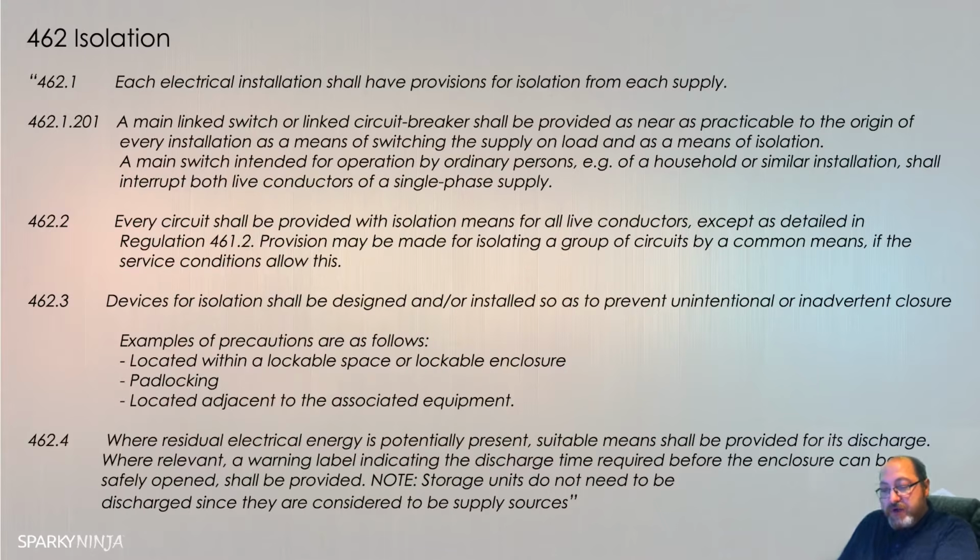Where residual electrical energy is potentially dangerous or potentially present, suitable means shall be provided for its discharge. Residual electrical energy, the common example of this is capacitors. So obviously you may notice many times you isolate a piece of electrical equipment and it takes a while, but the little LEDs are still lit and they gradually fade away. This is an example of residual energy discharging.